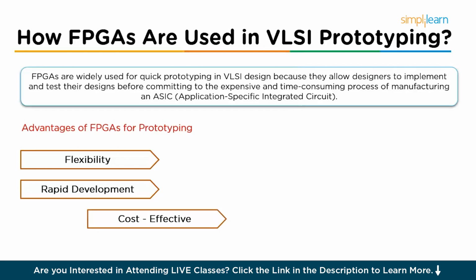This makes them an attractive option for prototyping new designs. The fourth point is real-world testing. Prototyping with an FPGA enables designers to test their design in real-world conditions, which is often more informative than simulation alone. This allows for the detection of timing issues, power consumption problems, and other real-world challenges.